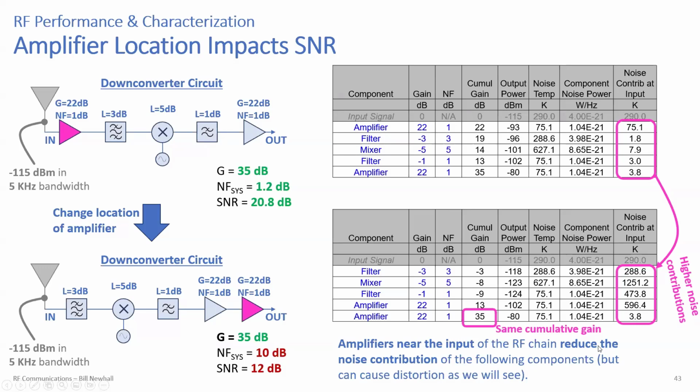Now, this is the reason if you have DirecTV or some other satellite service, out at the antenna, before that long cable that comes down to the satellite receiver in your house, there's a low noise amplifier to put it right up front, before all of the cable loss. So you want that amplifier way up front, and actually there's power on that coax usually going up to the antenna, so that LNA, that low noise amplifier, can be powered up there to put the gain right at the antenna before the loss of the cable, and that improves the noise figure of the whole system.